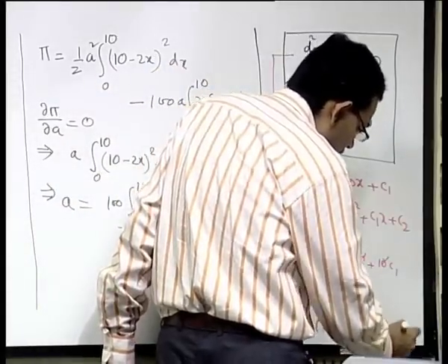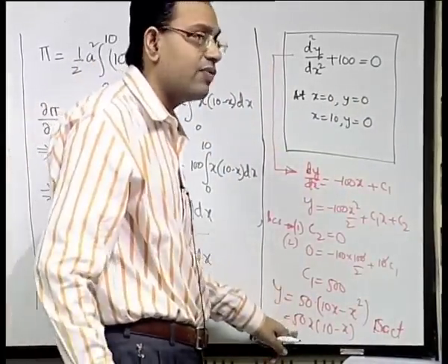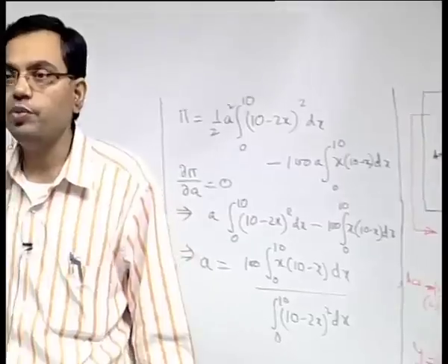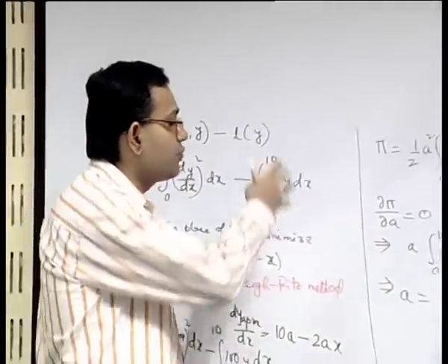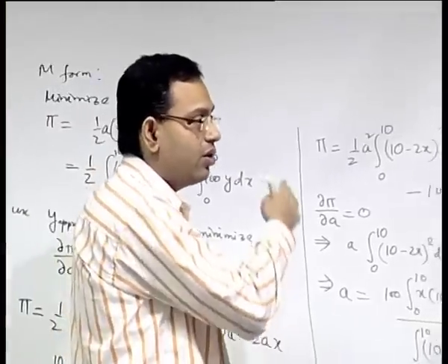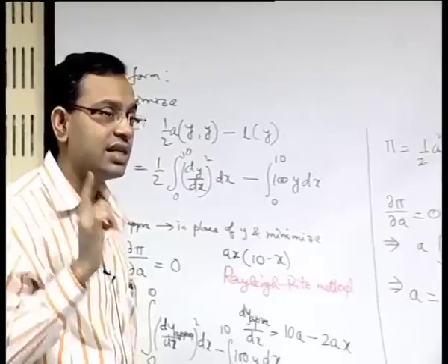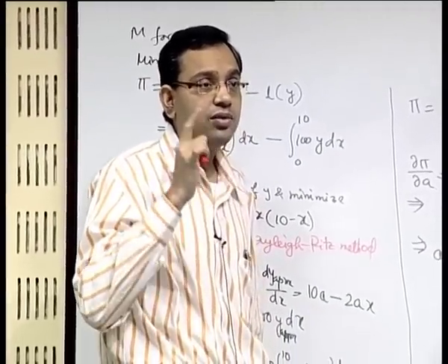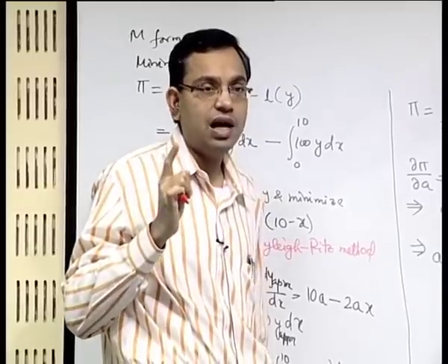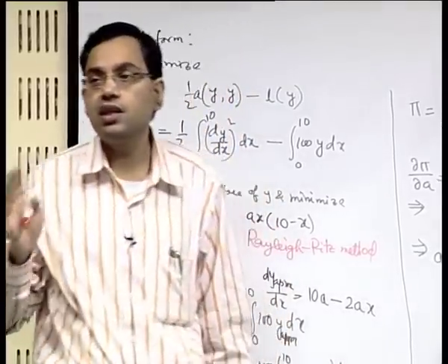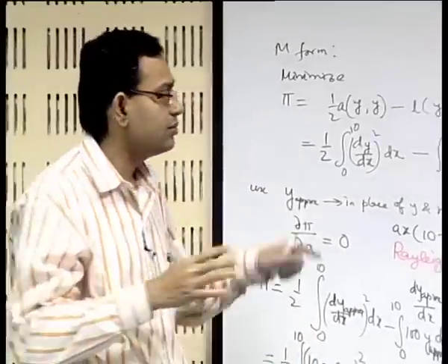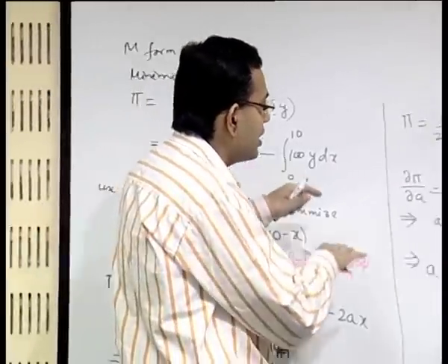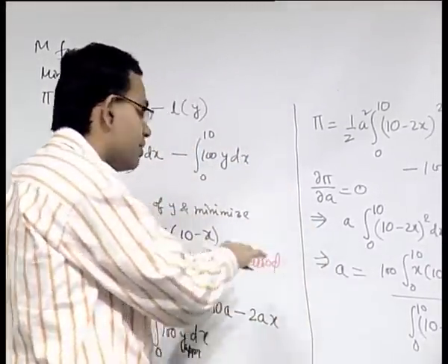The reason is that the exact solution is itself a second order polynomial form, and you have chosen the trial function also to be a second order polynomial form. So, we have used 4 methods actually, and in all the 4 examples we have used the same trial function, which is the second order polynomial function. Our objective was to find the unknown coefficient in that trial function, so that the error is minimized in some way. In 3 of the cases we have gone through the route of the weighted residual method, in another case we have gone through the route of the Rayleigh method.